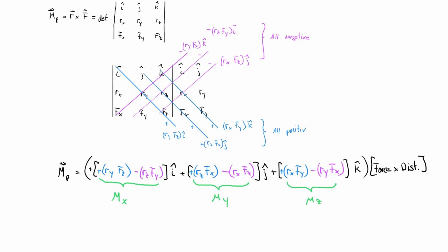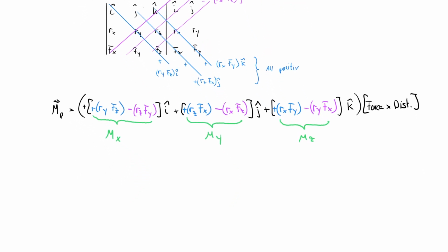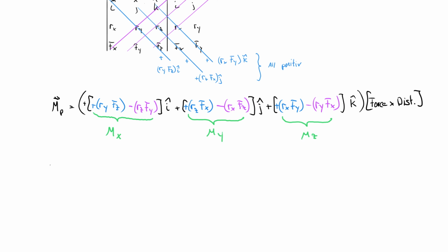And so let's remember that the moment about the x-axis is described by this term, the moment about the y-axis is described by this term, and then last but not least, the moment about the z-axis is described by that term. But of course, we can use this with our regular vector knowledge and calculate the moment's magnitude, right? The moment's magnitude is nothing else than the square root of mx squared plus my squared plus mz squared. And I think I explained that a few times, that you can always use Pythagorean in 3D. So here you have that once again, just as the magnitude of the moment.